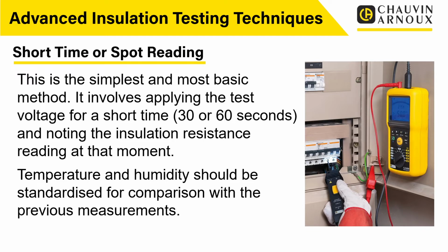And a lot of the testers that we provide at Chauvin Arnoux will have a timed feature in there, so that they'll have a timer and they'll let you carry out the test, and then it will take the result after a set period of time. So what that time is does depend on the insulation that you're using, the test voltage and the characteristics. But the key to this is you need to allow enough time for that insulation resistance reading to stabilize. If you're looking at the display and the insulation resistance reading is still changing, it's still going up or going down, you need to have a look at that and think, actually, I need to apply a bit more time to this.